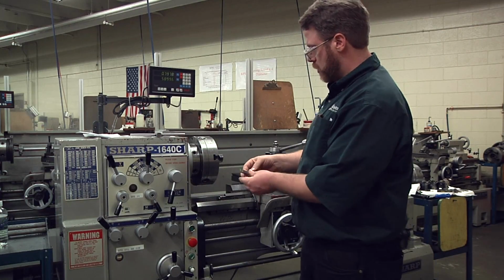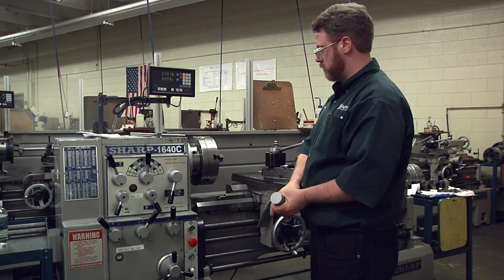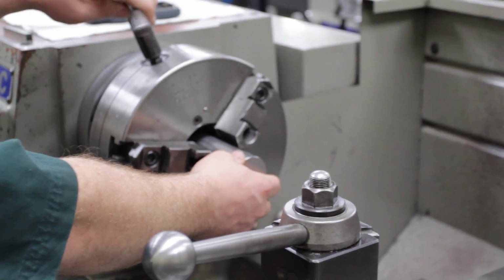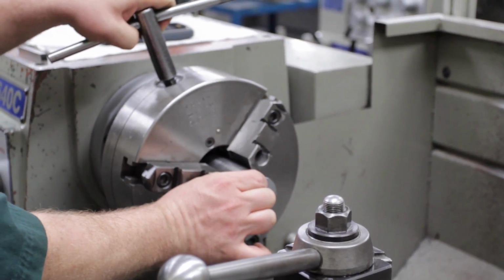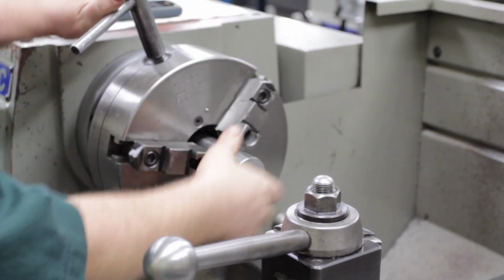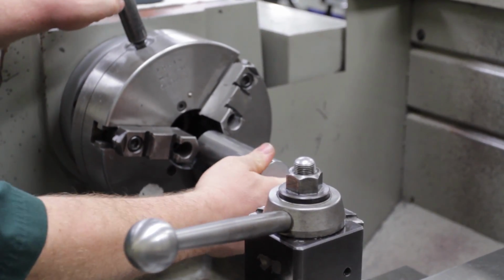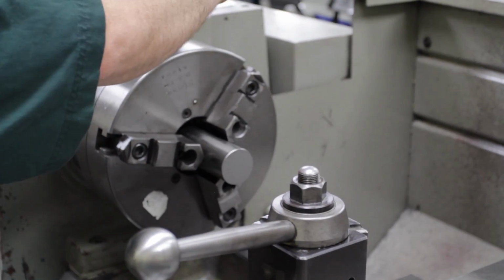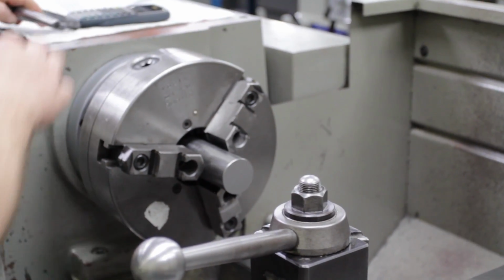The next thing is to get the workpiece in the machine. We're going to use a 3-jaw chuck here for today's demonstration. We're going to put it in and leave it stick out about the diameter. If it's 1 3/4 diameter, leave it stick out about 1 3/4 inches. You don't want to have it sticking out too far, because when we cut the end of the part, you're going to have a lot of deflection. To make it a nice, strong, sturdy setup, only leave about the diameter of it stick out.